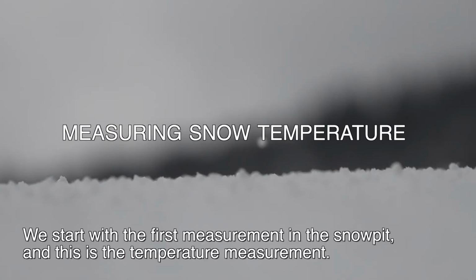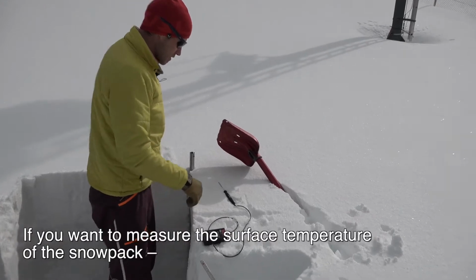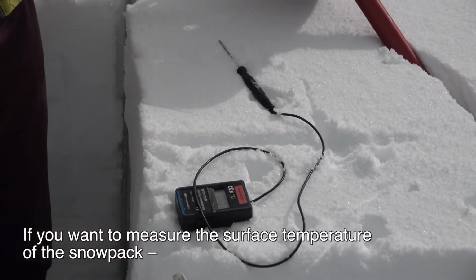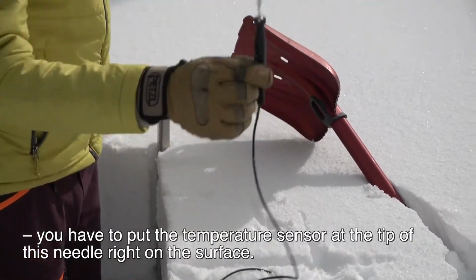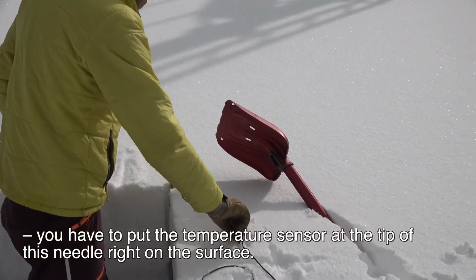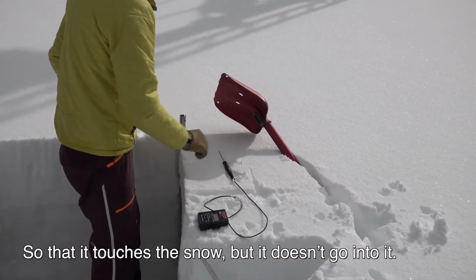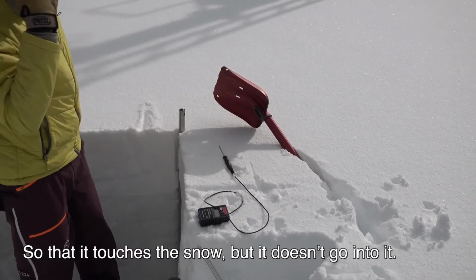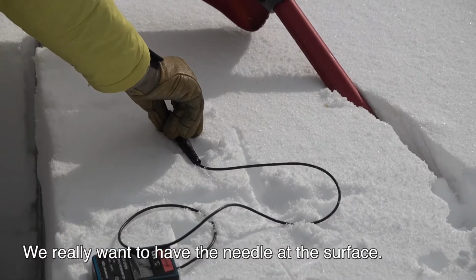We start with the first measurement in the snow pit, and this is the temperature measurement. We start with the surface temperature. If you want to measure the surface temperature of the snowpack, you put the temperature sensor, which is here at the tip of this needle, right on the surface, so that it touches the snow, but doesn't go into it. You want to have the needle at the surface.